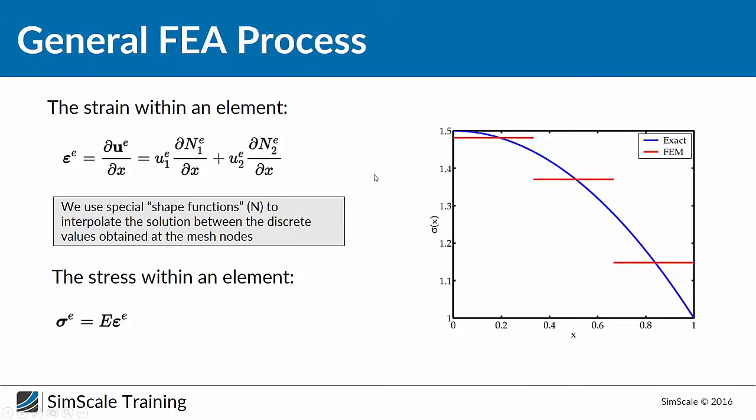We cannot expect the same things from an analytical solution as we do from a finite element solution, and the other way around. And if you take a look now here, you will see that we are facing another problem. I mean, we have the values for the nodes or for the elements, but we don't have any information about what is happening in between.